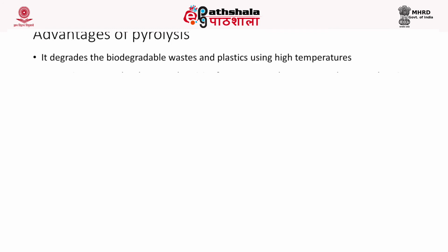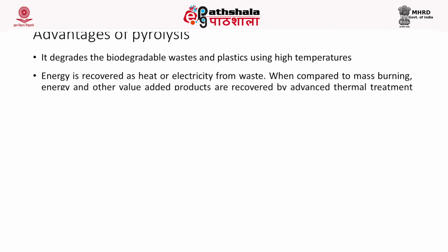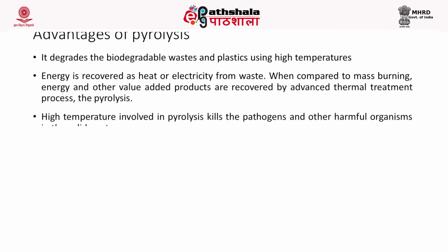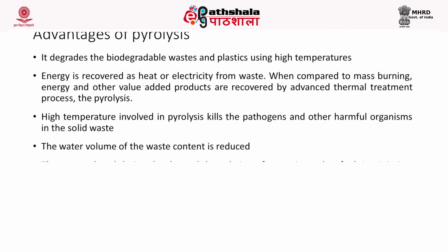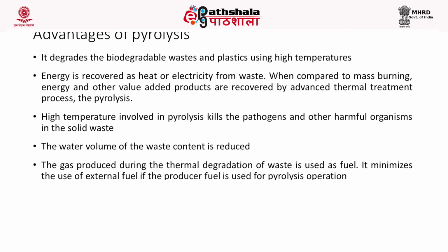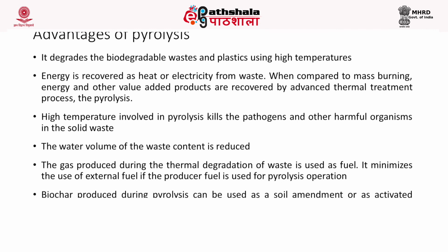Now, let's look into the advantages of pyrolysis. First, pyrolysis treats biodegradable waste and plastics at high temperature. Now, energy is recovered which can be used as heat or electricity. When compared to mass burning incineration, energy and other value added products are recovered from this advanced thermal treatment process. Now, high temperature involved in pyrolysis will obviously kill the pathogens and harmful organisms. The water volume of the waste will be reduced.